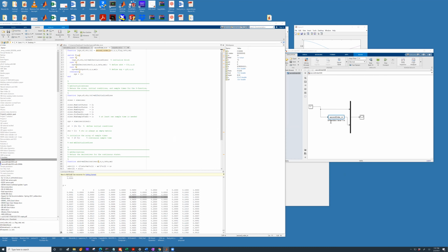Just imagine that you have a C code written for Arduino. You want a certain algorithm to be implemented on an embedded system like Arduino, but you want to use the exact same C code inside the Matlab environment to see if there are any issues with it. If you want to tap into the data, inspect the data, plot the data, you won't be able to do that with an Arduino. So you can take the C code, wrap it inside the S function, and run